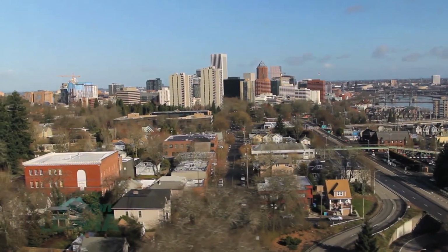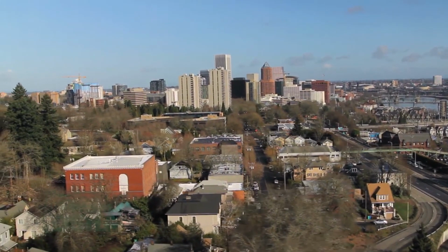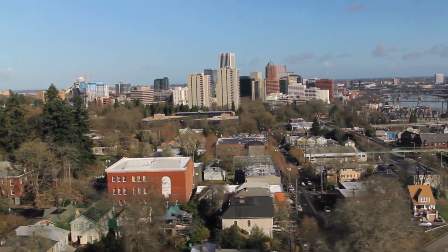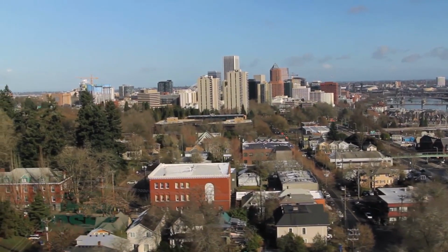And rescue plans have to be modified depending on the situation of the roof that you're working on, whether you're just on a single-story residential home or if you're on a 4-story commercial complex. Typically, those situations are going to be so different. You're going to have different equipment at each one that would facilitate being able to perform a rescue if needed.